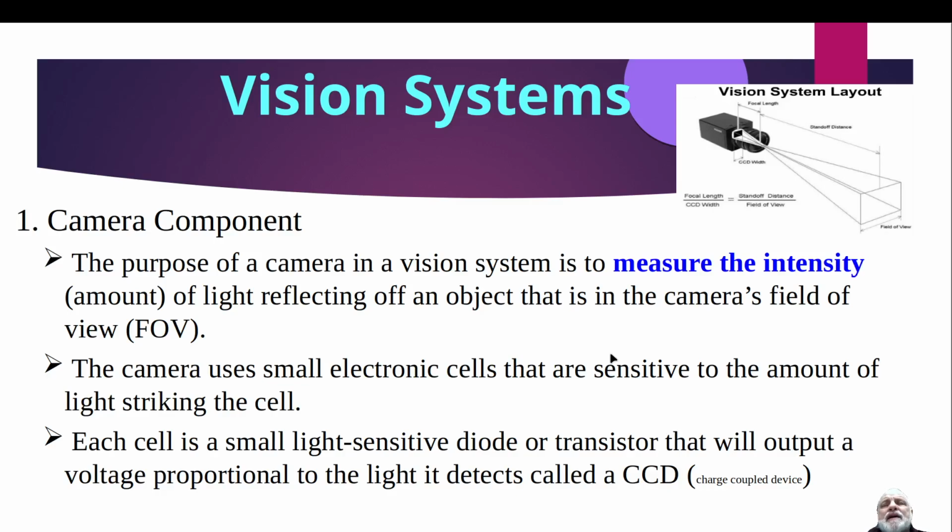Okay. When you talk about the camera, you have like the body of the camera, which has the CCD, which is referred to as a charge coupled device. What this means is that the intensity of the light charges these. It's usually made up of photoresistors or photodiodes, and so the light needs to hit that. But then you also have the lens, and then there's something called the focal length. So the focal length is the distance between your CCD and your lens focal point.